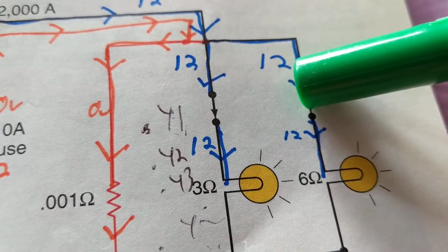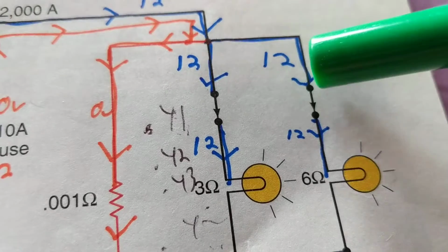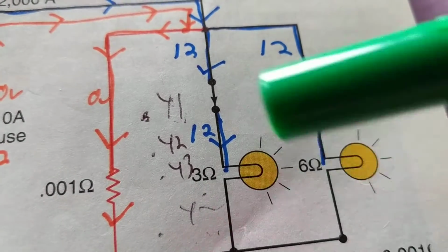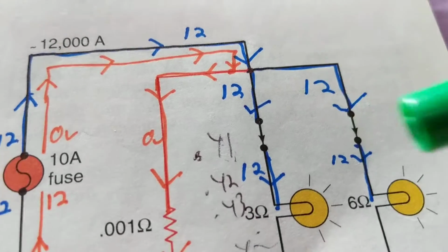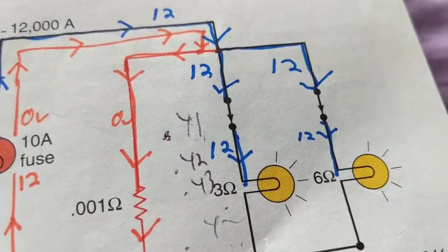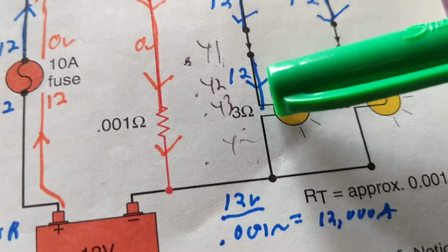In this case, maybe the switch. Maybe this wire broke off. Maybe this wire after the switch. Maybe the wire before the switch. Maybe the ground. Maybe this one goes to ground. Maybe this broke. I come over there, and guess what? I see both lights not lit. Both of them. What could be the problem?